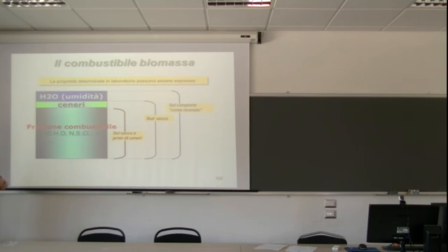For the reason I told you, water is a part that can be 5% of moisture, and in this case it's not so different speaking about the as received or dry basis. But if water is 50%, and sometimes it happens, it's very different to speak about as received and dry basis.